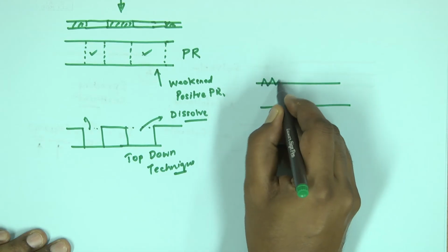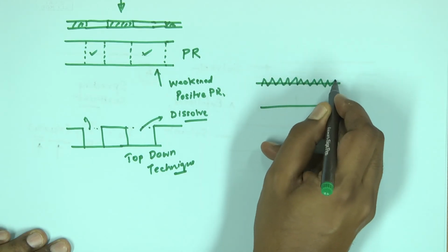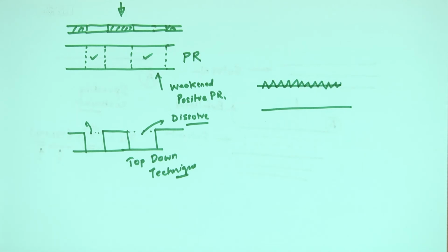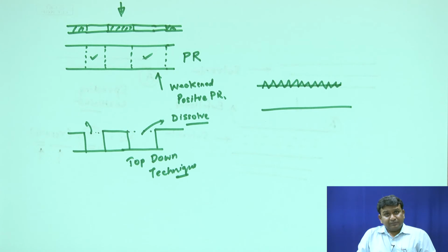On a non-wettable surface, if you have an ultra thin film, we also understood that you have fluctuations on the surface, which is attributed to the internal kinetic energy of the molecules, and these fluctuations typically are flattened out because of surface tension or the so called Laplace pressure.